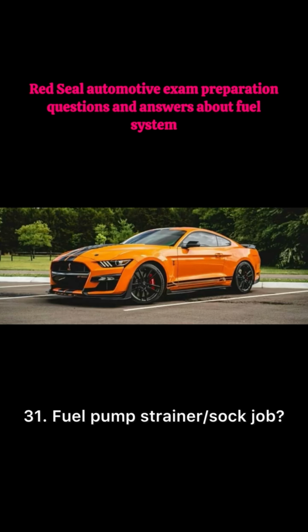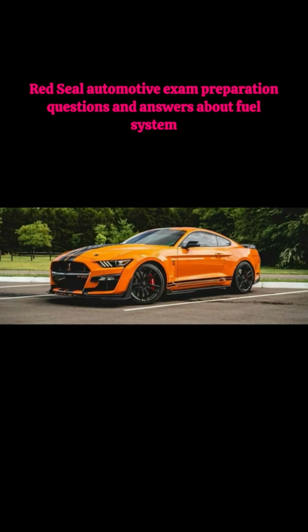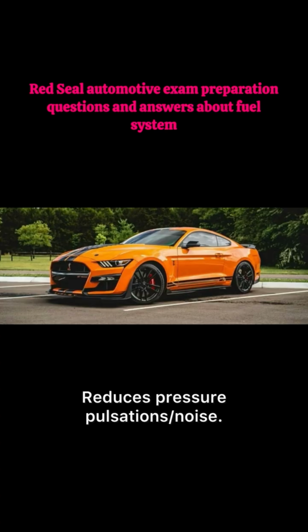31. Fuel pump strainer sock job. Filters debris before pump. 32. Restricted fuel filter symptom. Loss of power under load. 33. Most common in tank pump type. Turbine or gerotor pump. 34. Fuel pulse damper purpose. Reduces pressure pulsations, noise.